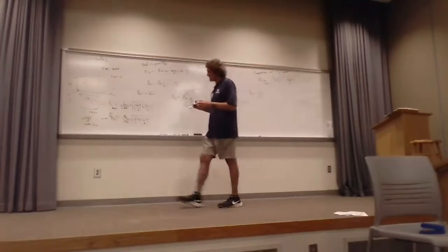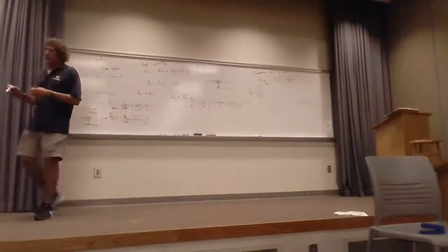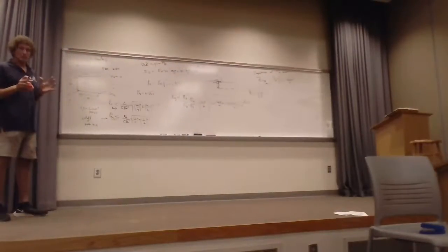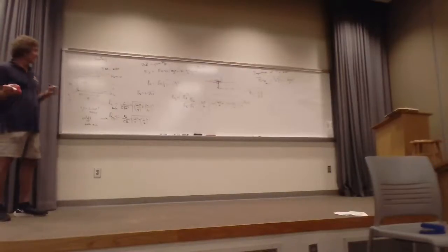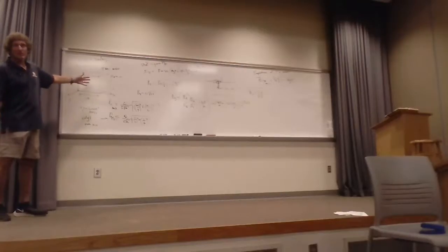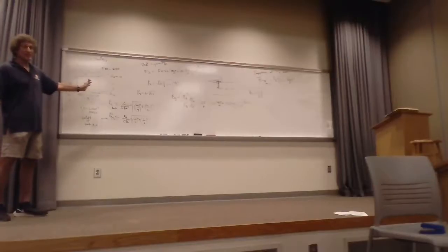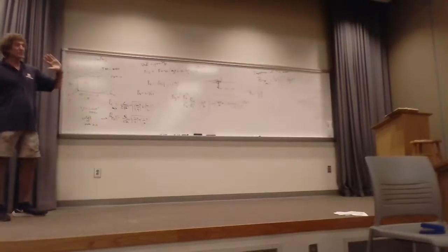Also, I don't want to spend a lot of time on this, when you're talking about the different modes and the different field structures, here's something that I don't think Dr. Wentworth would want me saying right now, but I'm going to anyway. Nobody sends a 1-1 mode down a rectangular guide, usually. You only operate in the 1-0 mode. All right, I'm going to say this, and it would not be a TM, it would be a TE mode. The reason is because for TE mode, once you get over the excitation frequency, only that mode can develop.